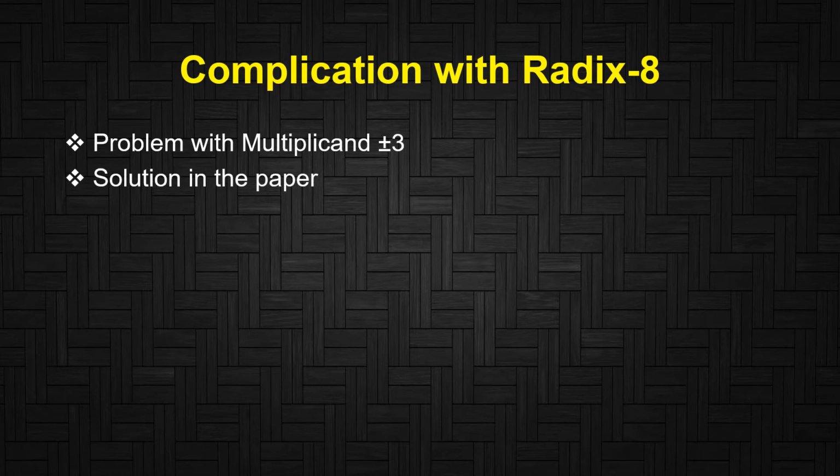So what's the solution for this problem? A solution is that we round it off to the nearest power of 2 by shifting. Moreover, the said approximation is handled such that errors complement each other, in contrast to high radix approximation. Additionally, the concept of hybrid lower radix encoding is introduced to explore the accuracy energy trade-off for approximate booth multipliers.